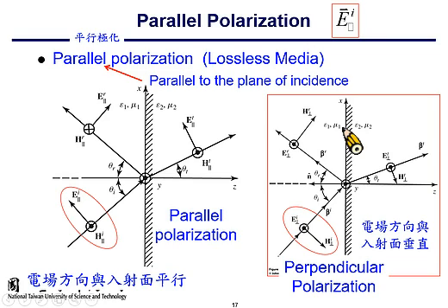The main difference is E-field orientation. For perpendicularly polarized wave, the E-field is pointing in the y direction, outward from this interface. On the other hand, for parallelly polarized incidence, the E field lies on the plane of incidence. Okay, plane of incidence is spanned by incidence, reflection, and transmission. So for this particular case, the plane of incidence is the xz plane. So the E field lies only on the